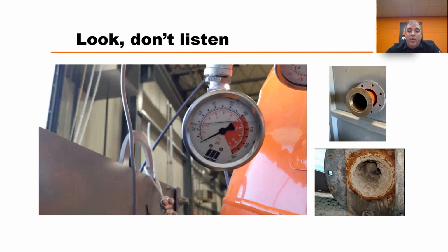So when your guys are going up and evaluating a system, watch the air gauge. Make sure it discharges very quickly from whatever the set pressure is down to 0. If it doesn't, and there's pluggage in those nozzles, you might as well shut the air cannon off, because all it's going to do is blast into that material, and eventually that material is going to collect back into the valve itself, and the cannon's going to break down, and it wasn't doing you any good anyway.